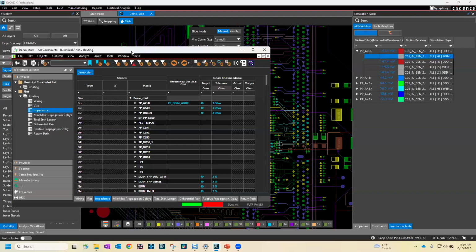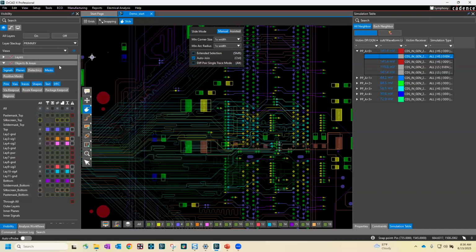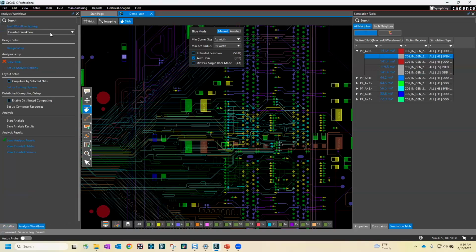And I would look at it like, if you can fix it, you may well fix it. Only in the situation that there's absolutely no way to fix that impedance discontinuity would you then have to look at the other analysis results. Let's say you first did impedance and you saw an impedance discontinuity.